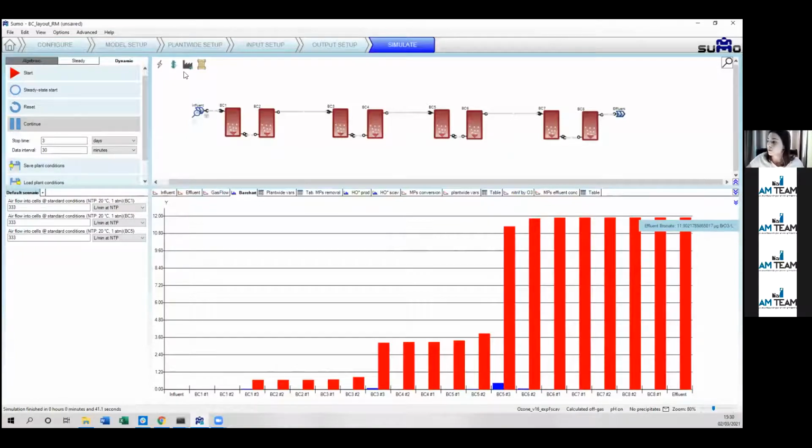And now we split the dose across 3 bubble columns and we got an effluent bromate of 12. So just by changing how we introduce ozone in our system, in our installation, we can lower the bromate formation by 30%.